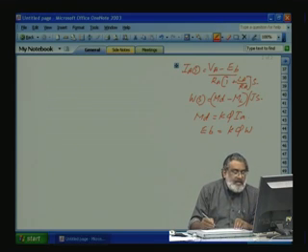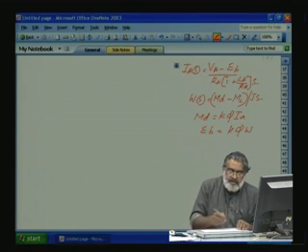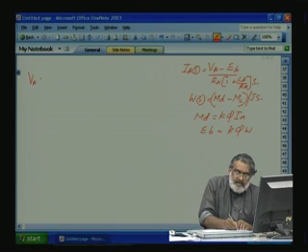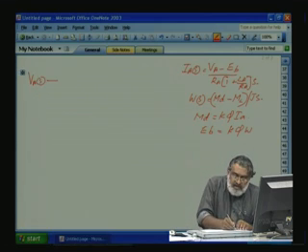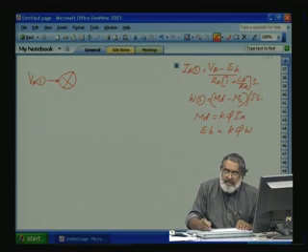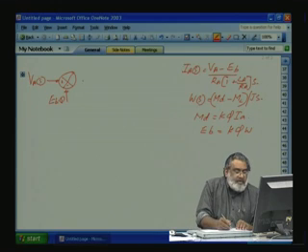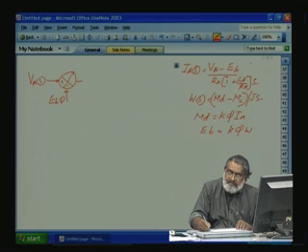So, let us write down our block diagram. So, we have VA(s) we are giving here, and if you see VA minus EB, so this is plus, this is our EB, VA minus EB, this has to be multiplied by 1 by this one.